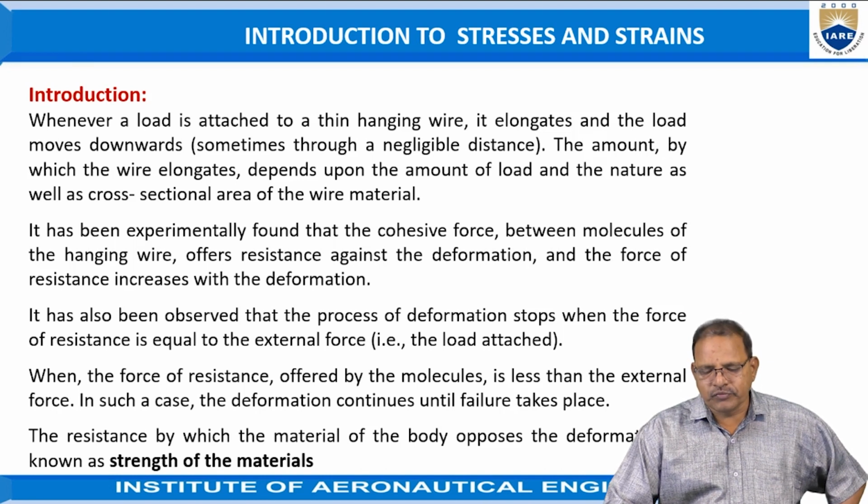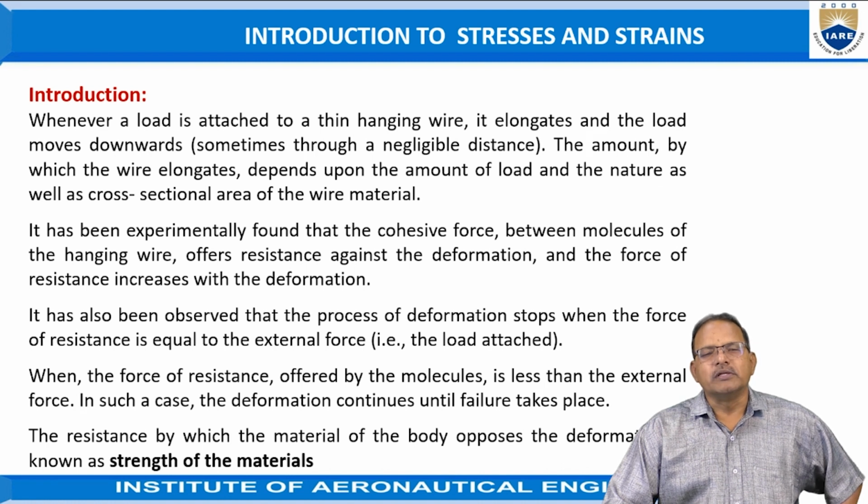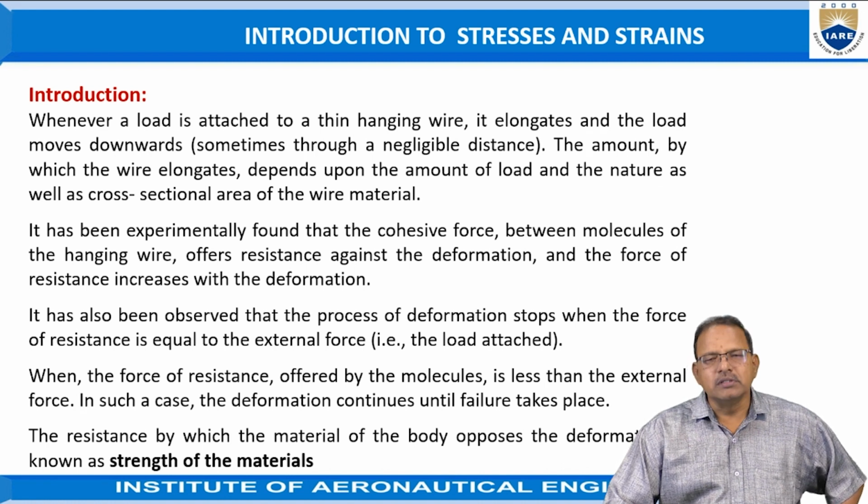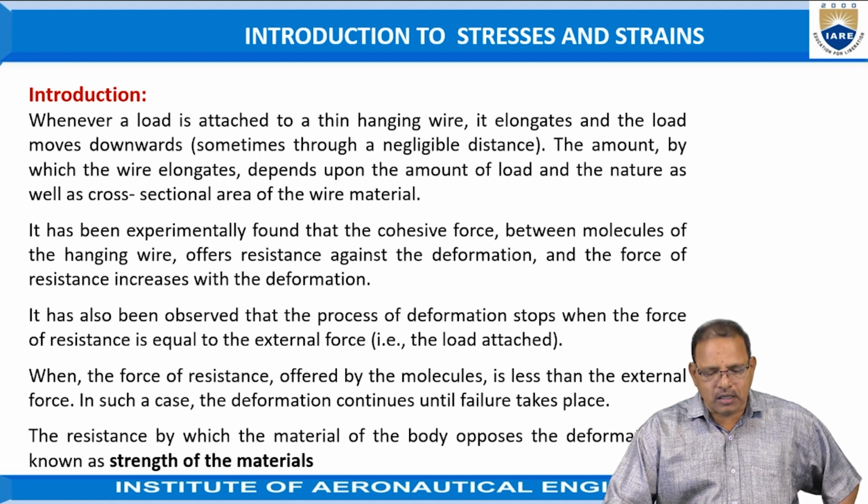It is only because of the cohesive forces between the molecules of the hanging wire, which always oppose the deformations, or in other words, offer resistance force to the deformations. When the resistance force is equal to the applied load, the deformation stops. But if the resistance offered by the molecules is less than the load that is applied, it elongates further and breaks the wire.